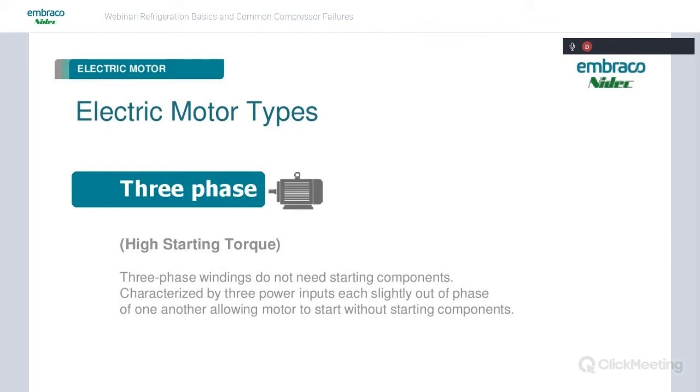You just need a large heavy duty, not a relay, but a contactor, a large heavy duty switch just to turn it on and off. And then the 3-phase power does the rest. These are high starting torque and high running torque by design. So of course you're going to see these on very large 3+ horsepower compressor motors. Like I say, a lot of your commercial air conditioning technicians are more familiar with this. They're fairly simple as far as components go.